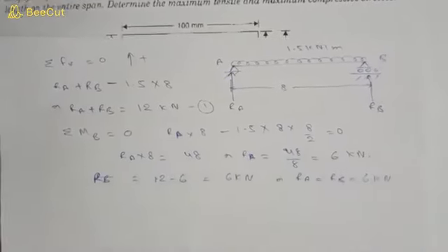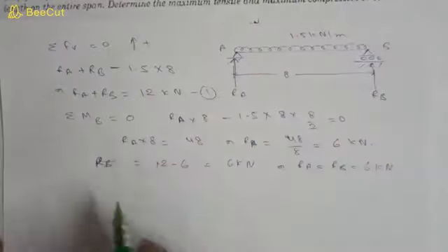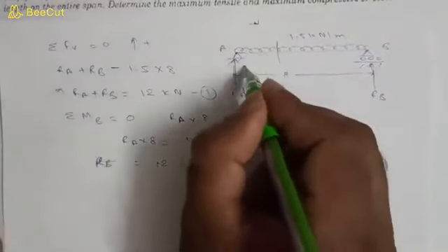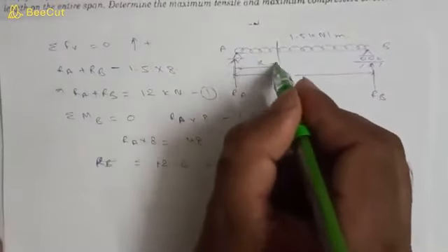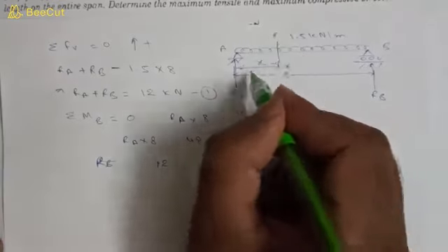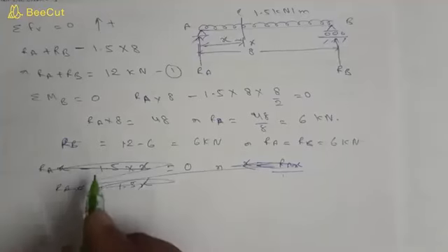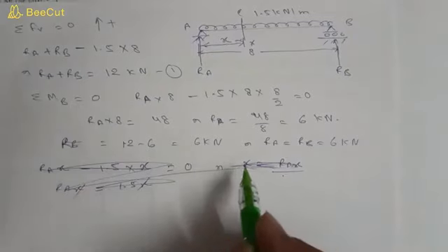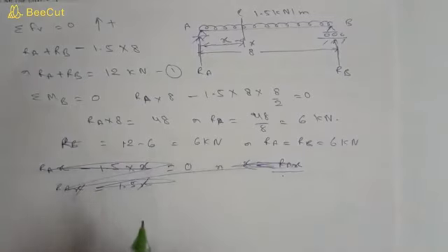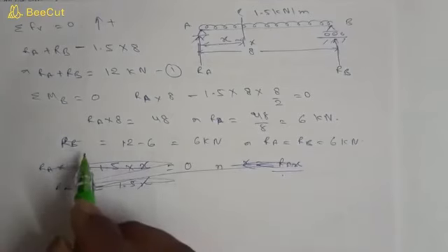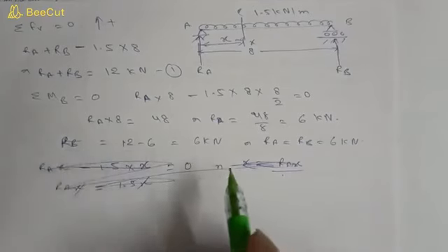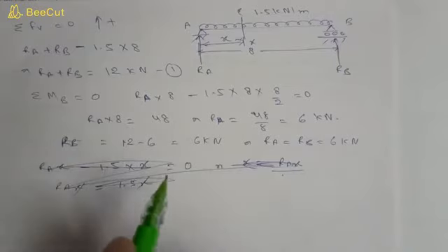Now the shear force for this beam at section XX, at X distance. Where shear force will be 0, the bending moment will be maximum. We need the maximum bending moment to calculate the maximum bending stresses. So we will calculate where the shear force becomes 0 so that we can calculate the maximum bending moment at that point.